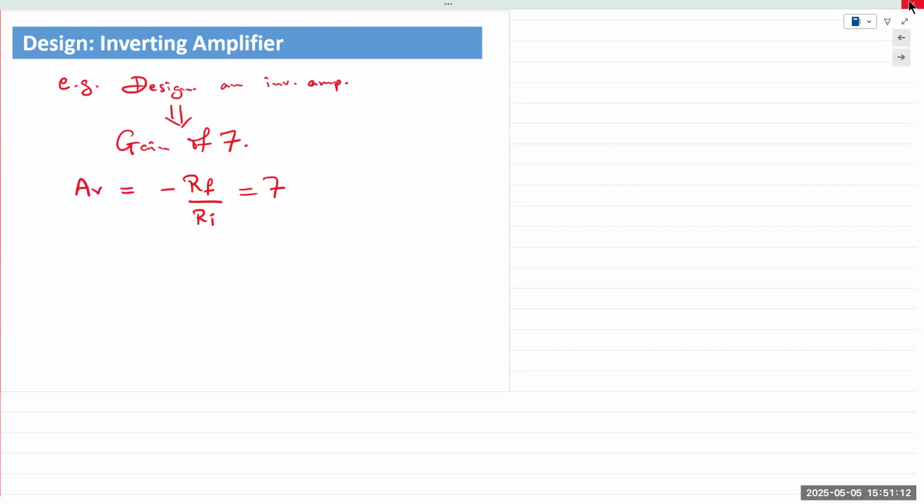Okay. Second point is that resistors are not available in all values. If you look at your textbook, in one of the appendices at the end, either appendix A or B, I can't remember which one, there is a standard set of values that resistors are available in from manufacturers. So there's 1, 2.2, 3.3, 4.7, and so on, and then multiples of those numbers, multiplied by 10, 100, 1,000, 10,000, 100,000. So you can get resistors only in those fixed values.